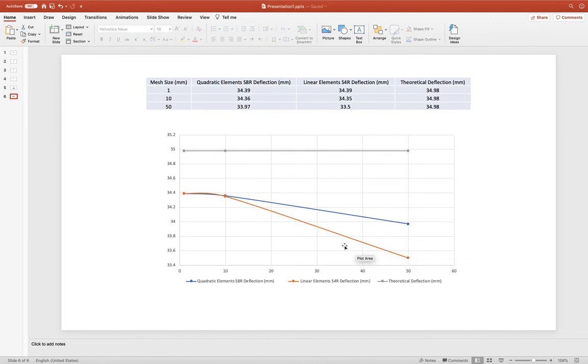But when you move much smaller, the difference becomes negligible in terms of the results. That's why this is what we call convergence study. If you're doing research in finite element, you need to show your advisor or the committee that you did this analysis, so that they tell you your modeling technique is right, that it's closer to the theoretical solution.